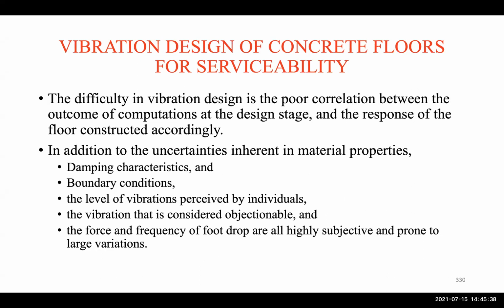Okay. Now, one of the difficulties in the vibration design is the poor correlation between the outcome of the computation at the design stage and the response of the floor constructed. So that's one thing. In numbers, everything may look perfect, but then, okay, what do we have in reality? In addition to the uncertainties inherent in the material, there are, of course, damping characteristics and boundary conditions.